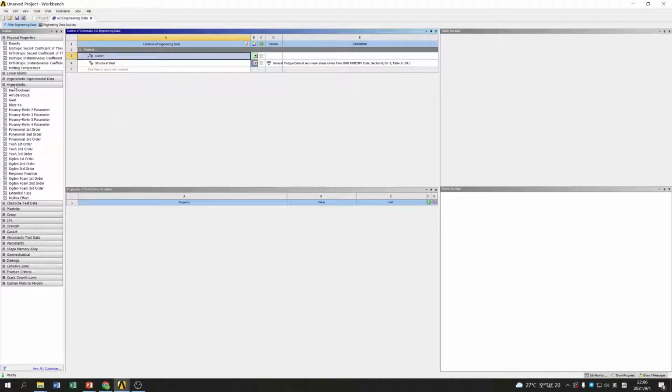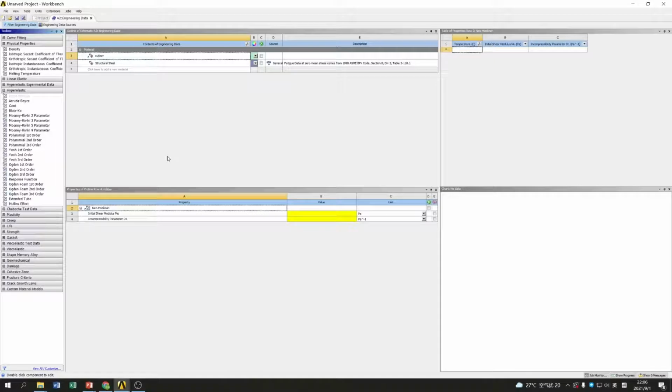And under the hyperelastic option, there are several hyperelastic material models like neo-Hookean and Ogden that we often use. The models are generated from material test data. It depends on what you're going to use. You may be able to find the data in academic books. I usually use EPDM, but today I just randomly create a material with the neo-Hookean model.